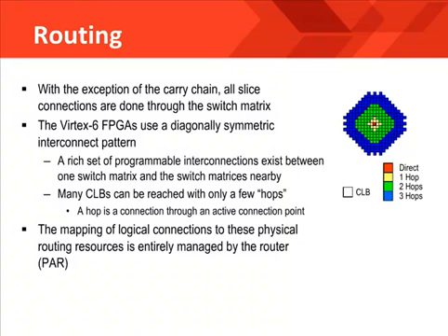You see, in between each CLB is a switch matrix which is designed to connect to other switch matrices as well as the neighboring CLBs. The possible interconnects are called PIPs, or Programmable Interconnect Points. Please note that proper use of global timing constraints, which are explained in the Essentials of FPGA Design course, are going to be required to communicate to the tools your timing needs.